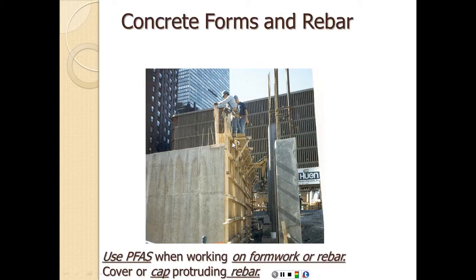When working on concrete forms and around rebar, to place rebar or to work on concrete work, use PFAS, which is the Personal Fall Arrest System. When working on formwork or rebar, cover or cap protruding rebar. So the rebar itself has to be capped to prevent the hazard of impalement. If someone falls on the edge of the rebar, that might penetrate through their chest or their midsection and can cause severe injury or even can kill them.